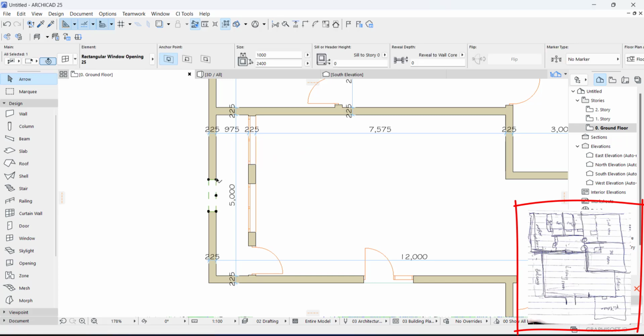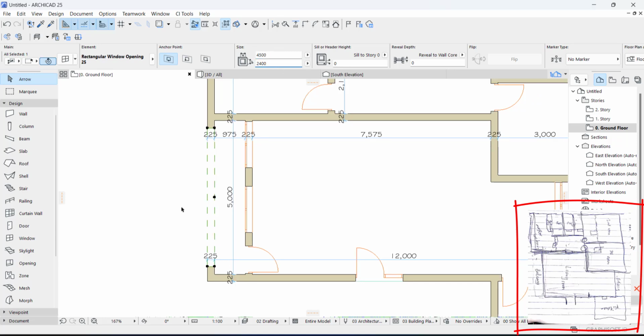Then since this space is that big, you just adjust. You click this, and the text palette will appear. Make sure you click this. This is move node. You move this node here, and you move this node here. Or if you think there's some space here that is added to your balcony, you can reduce it. You can reduce the width. Okay, this is 5000. Good. So you can reduce it to 45. You can see that is what it gives us.